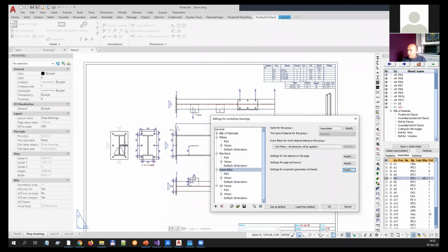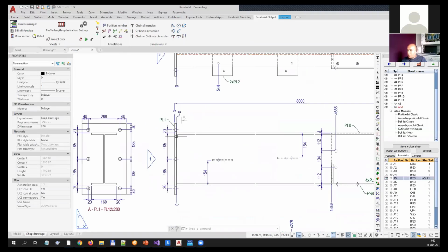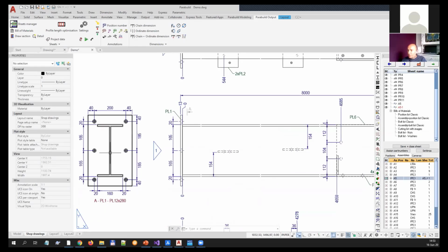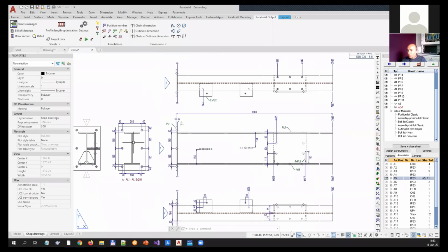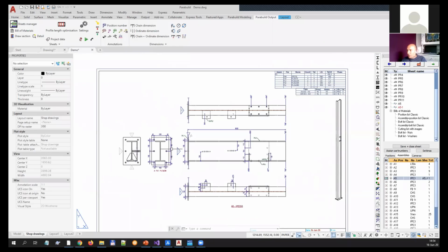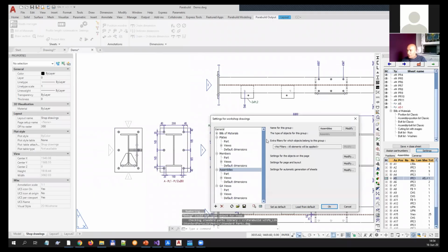Okay, I'd like to explain some more about the options here. You can see here this viewing direction for the section A. It's from inside part to the outside. So that's why the eye shape is drawn in full and not hidden. And I'd like to switch that. And I'd also like to, this is taking up a lot of space, these views together. So I'd like to enable more free location for these views.